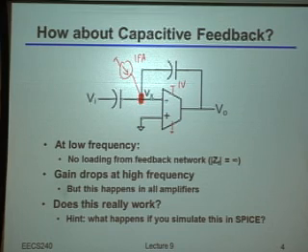And you've got 1 femtoamp of leakage there. Okay? Well, trust me, if there is no other path for current to flow, if you wait long enough, and somehow magically that femtoamp comes from some source that can go up to whatever voltage it wants to, well, indeed, this could go, for example, to 10 volts, or minus 10 volts, or 5 or 15 or whatever you want. Okay? Hopefully it should be pretty clear that if you were to put that into the DC input of your poor transistor amplifier with a 1 volt supply, it would die, right? It would do absolutely nothing useful.